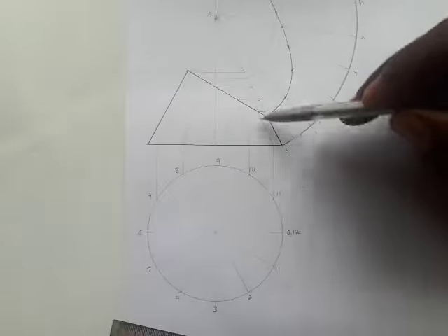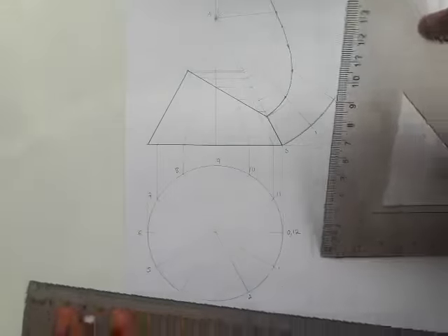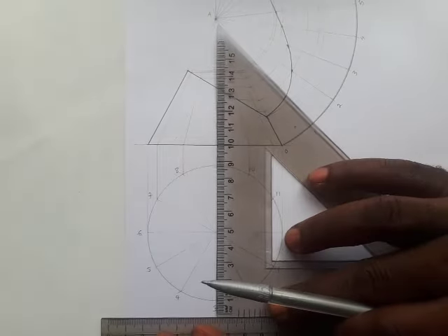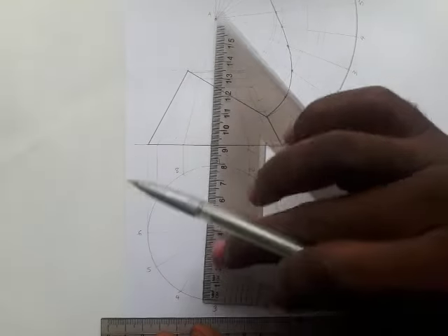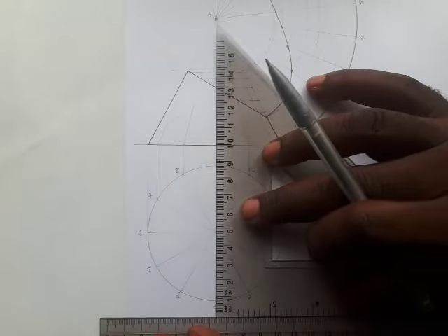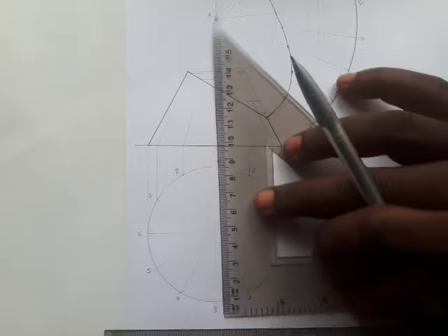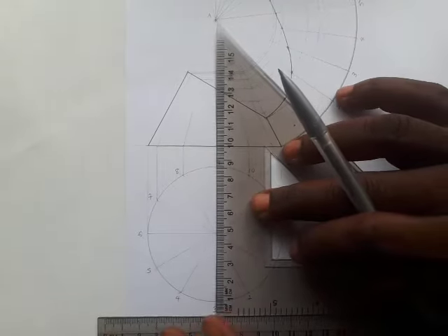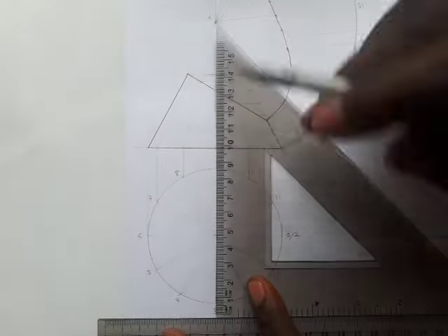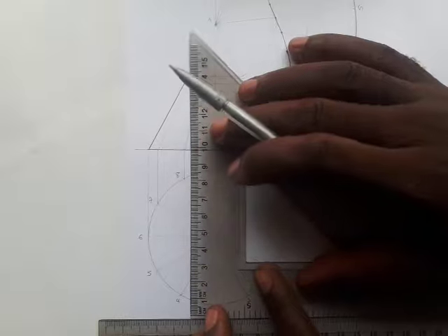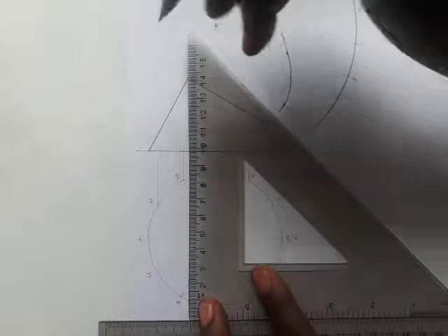All right, so let's do that, and I'll tell you how they coincide and how to trace out the points that form the circular opening or the elliptical opening, depending on the shape you get at the end of the day. So align your set square with the center line here. All right, so let's start with the first one here. So transfer lines to that point. Draw thin lines down.